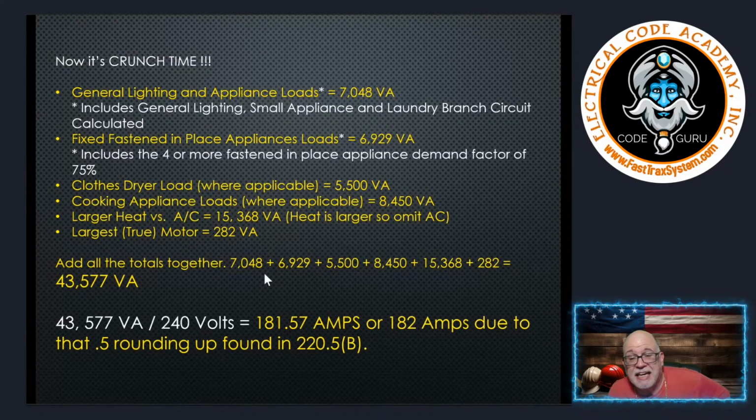The conductor cannot be smaller than 83% of the rating. If you have adjustments or corrections, you have to account for those, and they might cause you to go to a bigger conductor, because after those adjustments and corrections, you still can't have a conductor that's less than 83% of the rating of the service or feeder.